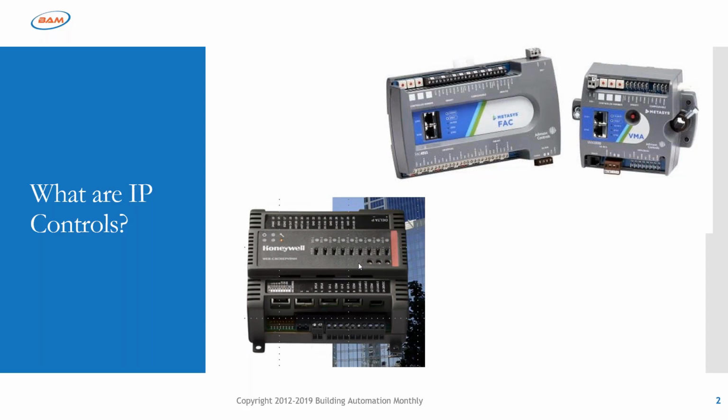So what happens is building automation data doesn't have quality of service typically associated with it. So if you start to overload a trunk, a network trunk, which we're not talking about field buses and trunks, we're talking about a trunk, which is a connection between two switching devices or two routing devices. If you start to overload that trunk with data, what's going to happen is now you are going to have an issue in that the switch is going to start dropping data.